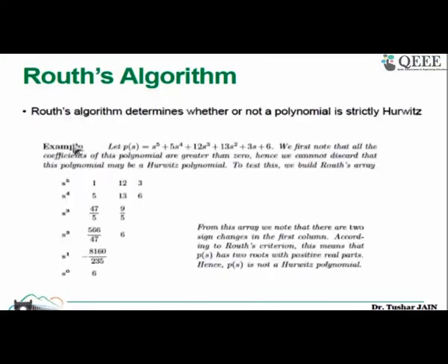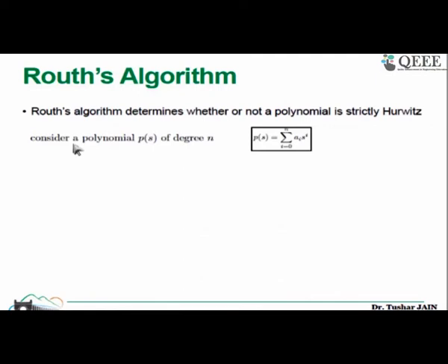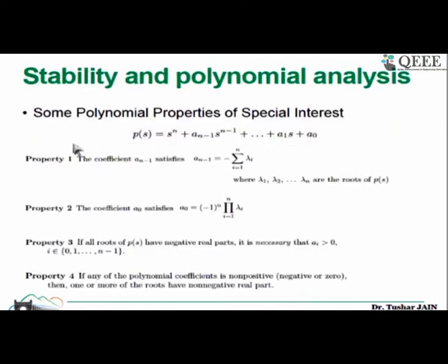So there's one question from RCPITMH. Is Routh criterion applicable for non-linear systems? I haven't seen so far, and in fact, first you need to see. I think the answer to your question would be in your question itself. So we started building this Routh array, or we started using this Routh algorithm, assuming that we have such kind of polynomial. Okay, and this polynomial is nothing but the denominator of the transfer function.